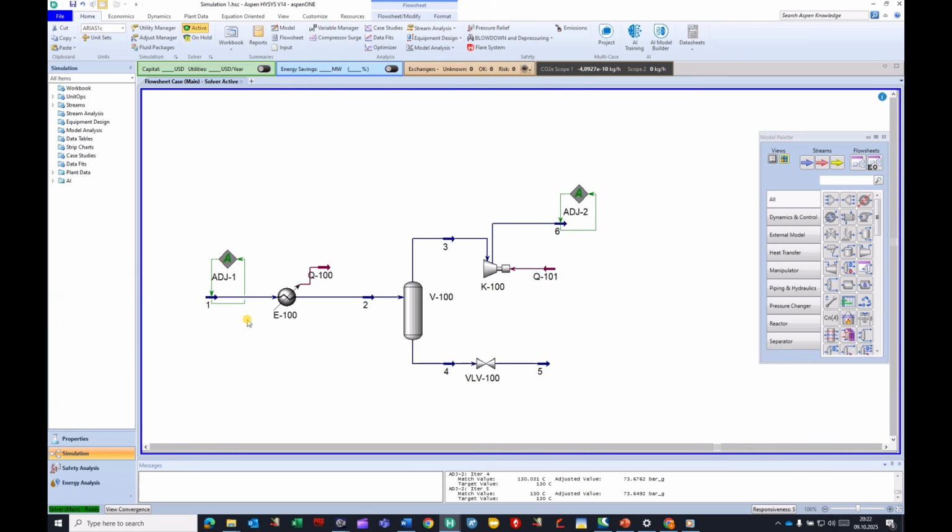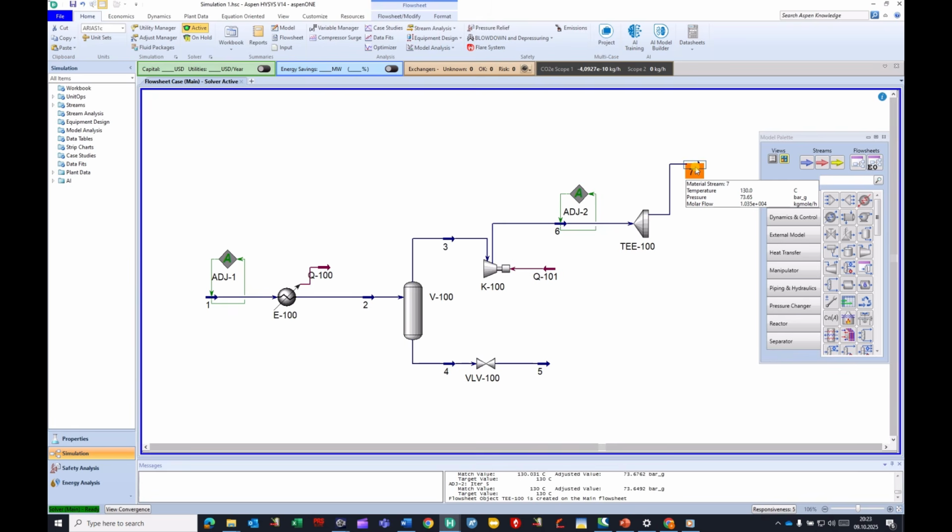The last remaining part of the simulation is the anti-surge line. Simply, the anti-surge line is the minimum flow protection for dynamic compressors. Here, our compressor, we assume, is either centrifugal or axial. You can also change the direction of the streams, and the equipment acts like a mirror with number 2 of the keyboard. And also number 3 will rotate the stream in the direction you want.